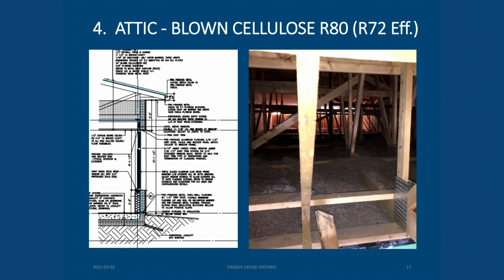The roof had two types of assemblies. There was a cathedral assembly, or technically an unvented roof assembly, and then a standard attic. So this is the attic detail here. You can see in this drawing on the side, you've got the attic insulation. You also have the continuous insulation on the outside running to the top of that layer, so that you have continuous coverage through the sheathing and the framing members of the trusses, all addressed by the exterior insulation here.